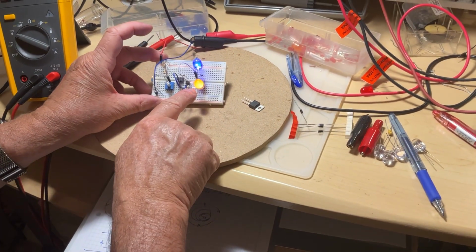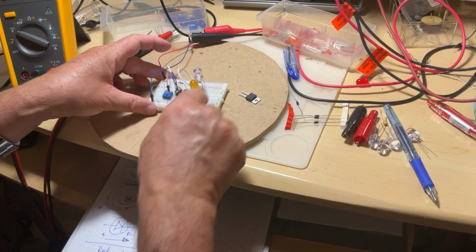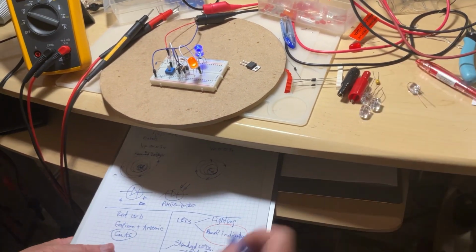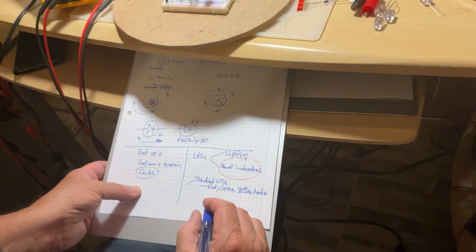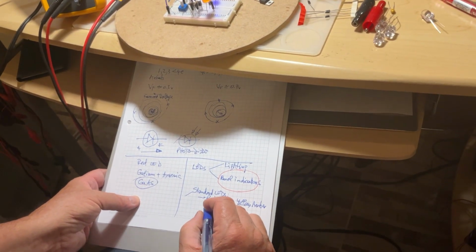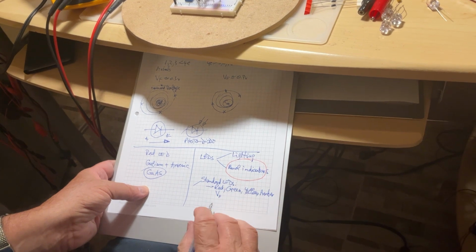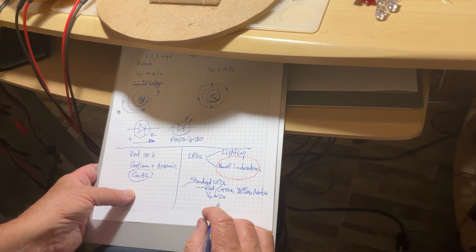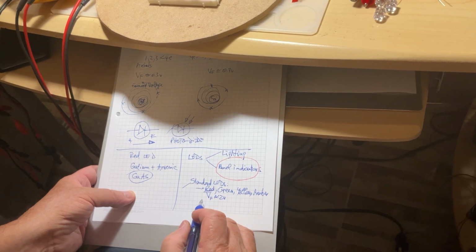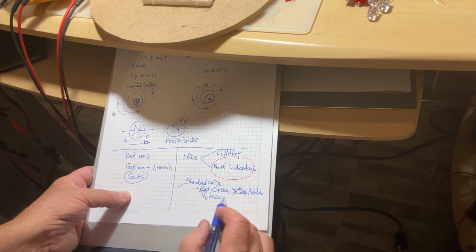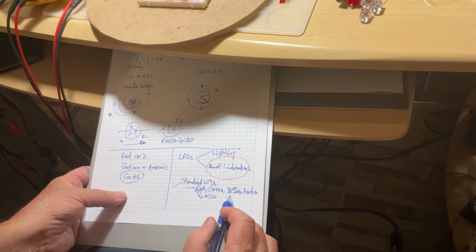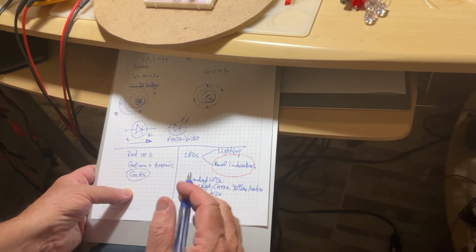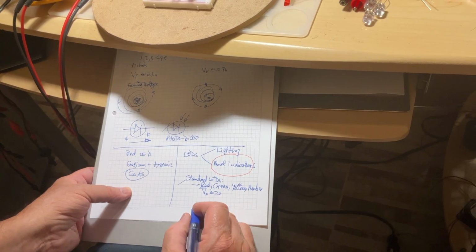That's the amber LED. Okay? Very good. So these are standard LEDs. What is common for them? The voltage at which they start conducting is around 2 volts. Some of them, like the red, are 1.7 or around, and some others, like green and yellow, may go up to 2.15. Okay? But we take the average, considering 2 volts is good enough.